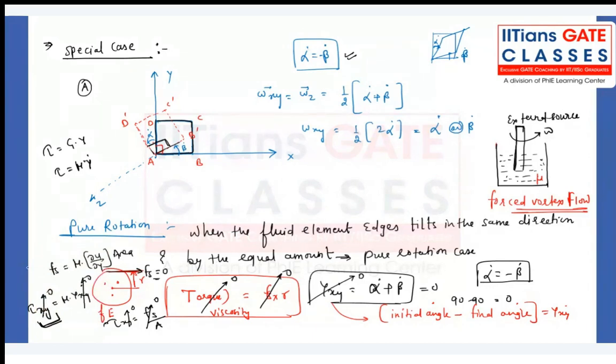Yes, for a static fluid, it will be zero. But that depends on, for the static fluid, whether it has been driven by the plate or not. If you are not at all giving any velocity to the plate, just what we have discussed, simple Couette flow, then straight away that is zero. No viscous force, no drag force will be there on a fluid element. In a static fluid, there cannot be any shear force. Remember that. Now, is it done, all of you? All of you have noted down?